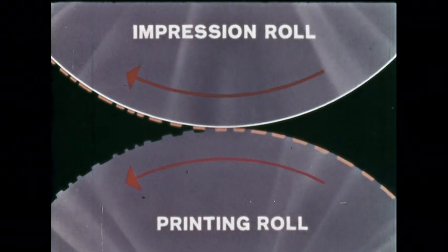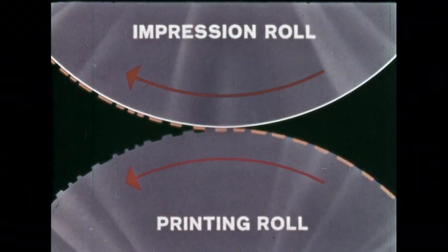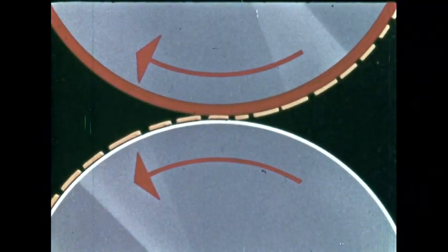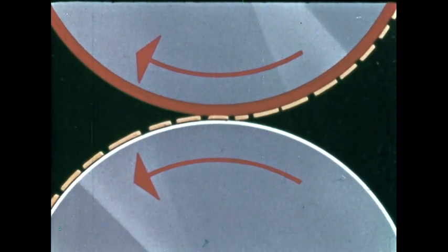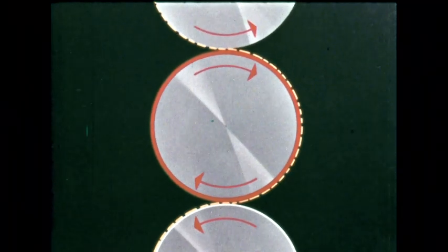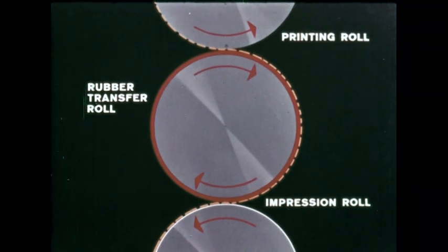Gravure requires a surface which is not quite so hard, so that when the plate is pressed against the material, the ink is drawn out of the depressions of the printing area. Offset lithography differs in that it uses an extremely hard surface, such as steel, with an intermediate rubber-covered surface transferring the image to the material. Apart from the inking and surface differences, the mechanical features of presses will be much the same for all the printing processes.